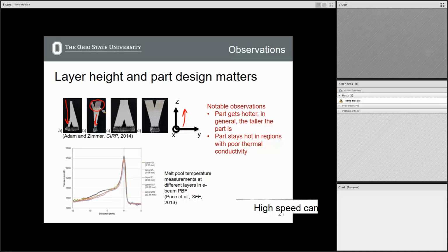This defect is oxidation. Oxidation comes from having some amount of oxygen in your chamber. We can't completely evacuate oxygen from the chamber. It's somewhere less than 0.1%, but there is some amount of oxygen in the chamber. And oxidation happens when you have oxygen and basically a lot of materials, but especially metals, at elevated temperatures for long periods of time. So you get things like this. You see this even to a smaller extent in this example. You see a little bit of oxidation here, but again, the neck down here is wider than it is in this one, so it's not as big of a deal.